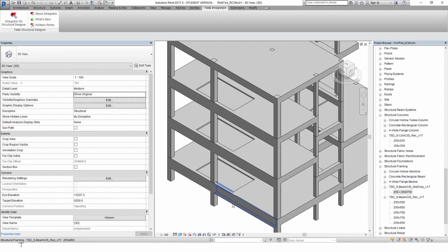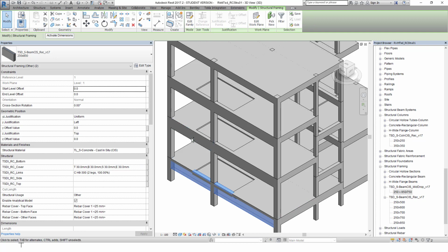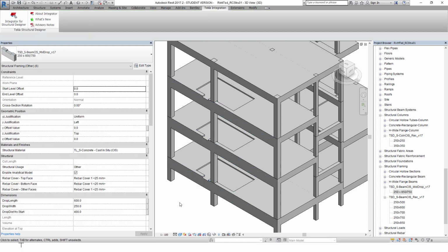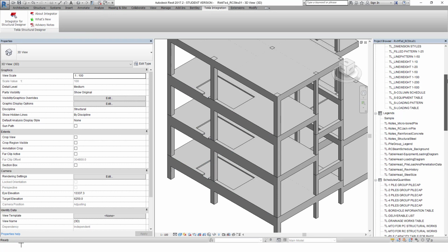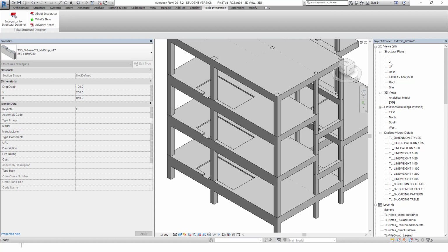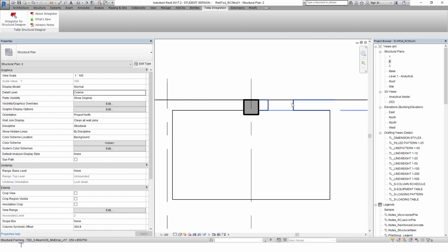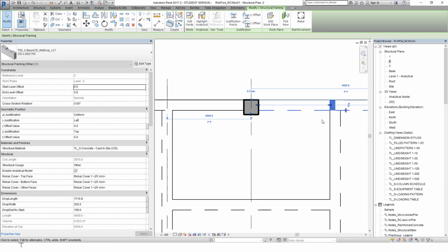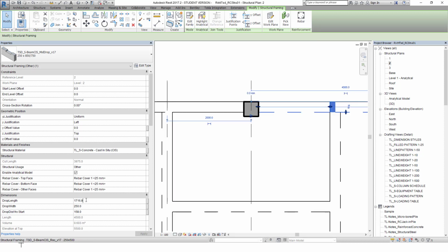So if you want to change the size, then select, then this beam also select and change the size. Change the types. Then whatever drops, we have to adjust it manually, so we can adjust it from the plane. Then we will come to here. What we need to do is this one, drag it here, drag it to the edge. Maybe sometime we can align it. The best way is measure it. The value will be 1750, and this one should be 125, because column is now 350, so 125, 175, I think.